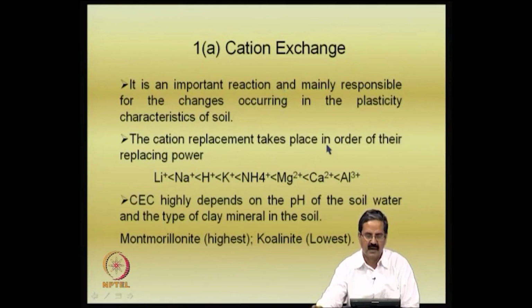For example, a sodium ion gets replaced by a calcium ion. If you have a sodium bentonite and you add a lot of calcium, then sodium gets replaced and it becomes a calcium bentonite. This is what is called cation exchange capacity.